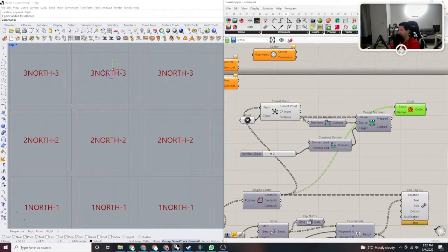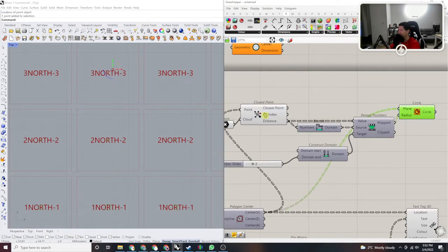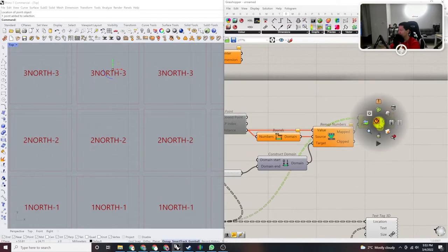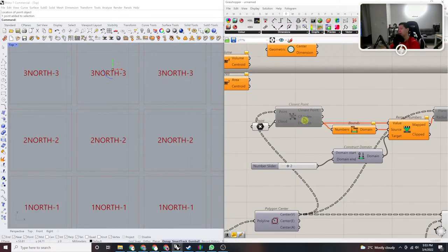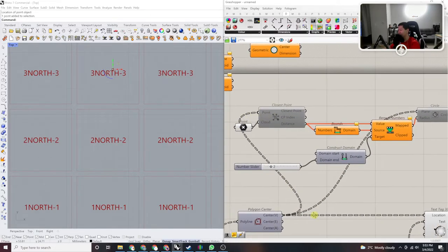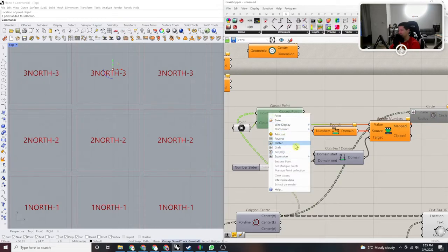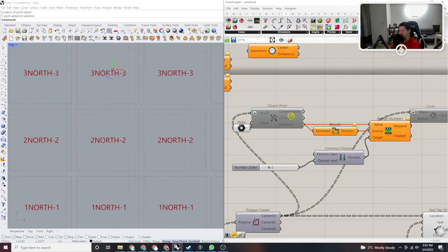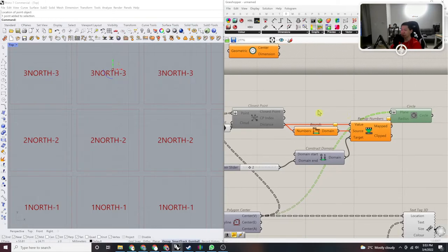And we can actually, I will disable this. If you're doing some flattening operations and you see that both of these are dependent, you want to try to cancel those, or try to disable them so they don't try calculating, because when one's flattened and one's grafted, the data will get exponentially larger, so it'll take more computational time.